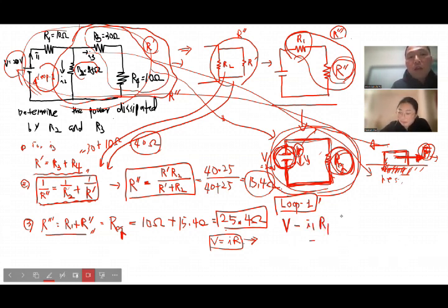and the resistor lowers potential. So you have to add the minus sign with the resistor, and that's why you have I1 and R1 with the minus sign. The second part is that resistor comes with the current I2, so that's I2 times R2 equals 0.